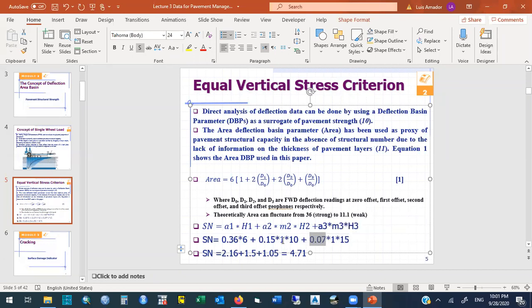And then you have something else that is here, the drainage, and it's a characterization of the drainage. You can assume it's 1 just for the purpose of this class. However, that is not true. We will see in pavement design what is the actual value, but this is just to show you that this is another way to characterize the strength of a pavement. In this case, for this example, the pavement will have 0.471. Values can go as high as 9.